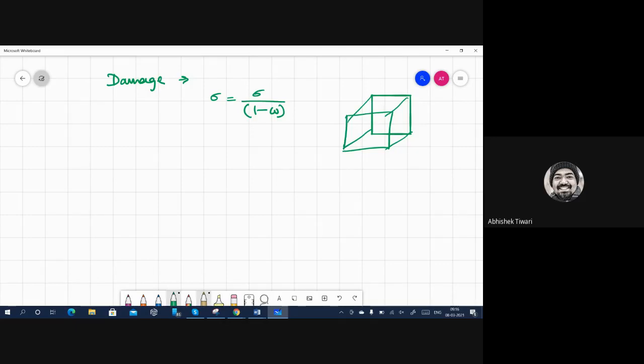So the real continuum mechanics defect in ductile material, let's say at room temperature, where the material is ductile and we are talking about crystalline material. One good example would be any BCC or FCC material, not HCP. As long as it is ductile, you will have three-dimensional voids, and these voids might be of different sizes.